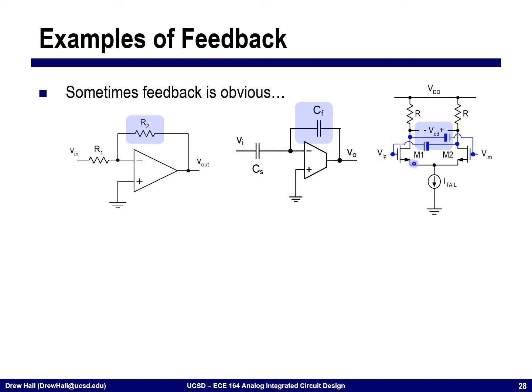In our differential amplifier, we saw an example with a technique known as neutralization, where we're trying to cancel the effect of CGD. We did that by taking the input and adding a capacitor to the inverting portion of the output. So the negative version over here, so these are cross-coupled capacitors. Again, we're coupling capacitors or resistors between the input and output in all of these cases.